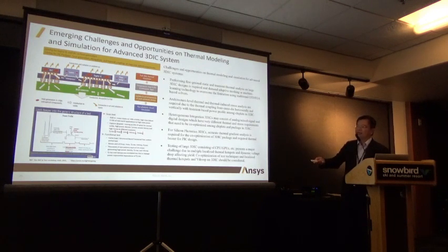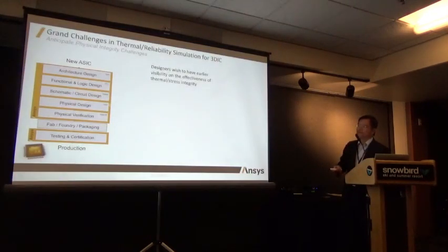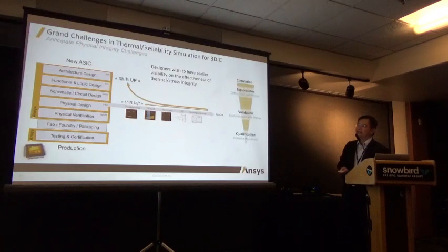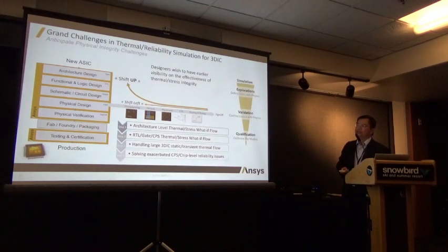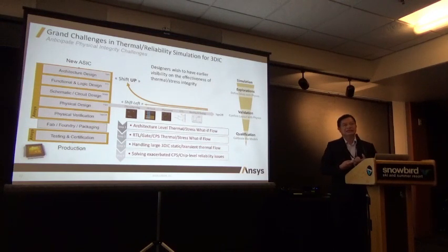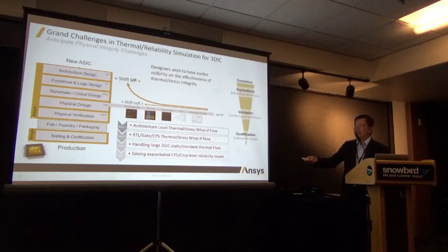So this is a big question, a big problem, big challenges for 3D IC testing. In summary, after talking to all the customers, there are several challenges. They need architectural-level, very fast thermal stress simulation, given the architectural design with different block placement and maybe the global routing, and from the thermal perspective, they need to trade off between design A and design B.